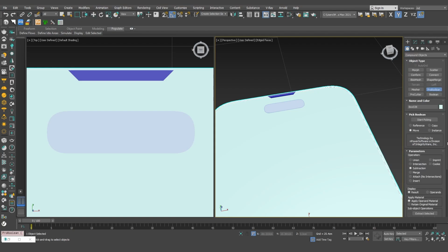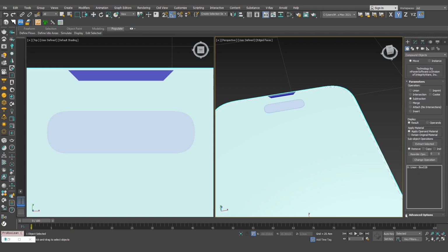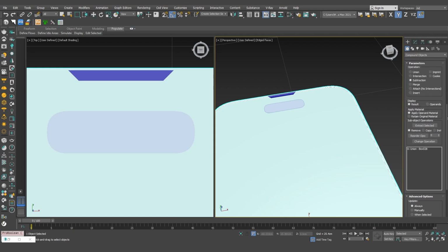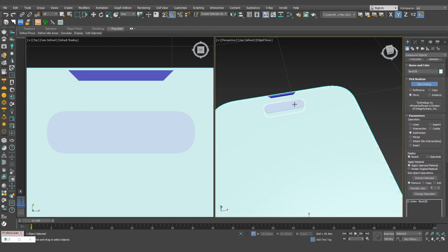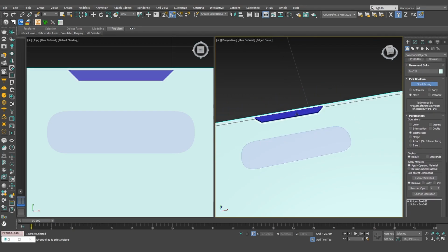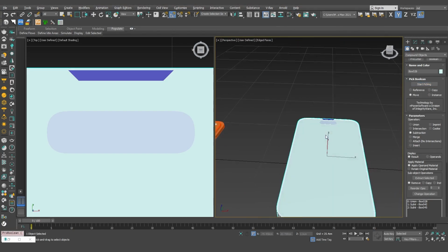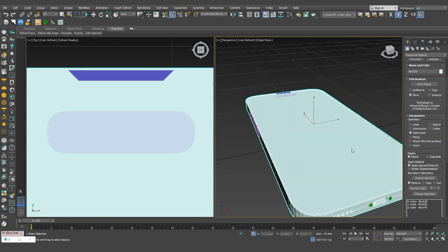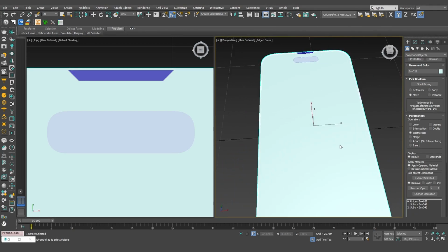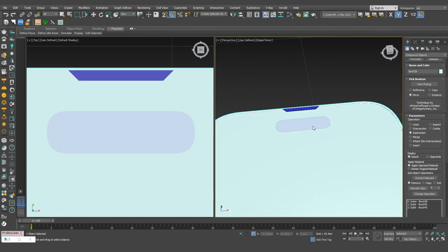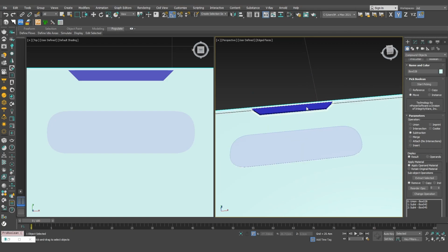Let's enable Pro Boolean again, and make sure to turn on no edge removal so edges remain clean. After applying subtract, I'll check for gaps. Everything looks fine. This one will get a darker material.